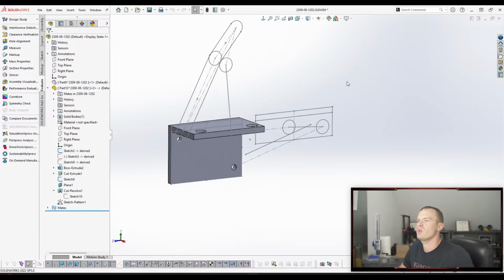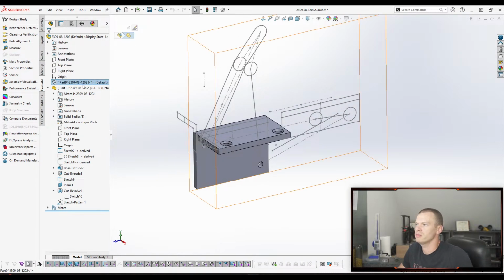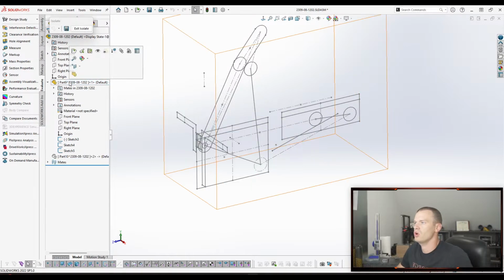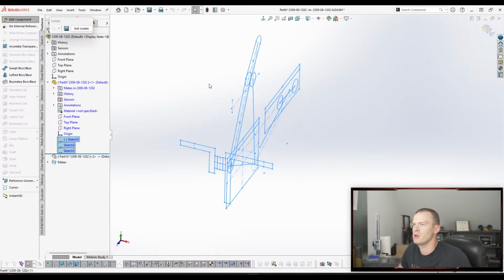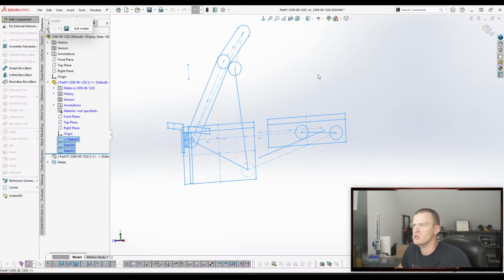All right, cool. So this is where we're at on our Hinge design, right? So we've created this kind of, I want to start calling this a folder part, because basically it's only here to hold all of our sketches, right? We've got 3 sketches that we've made up. So our primary one is this profile view where this morning we went through and figured out our linkage lengths, and then also we're designing it so that the links kind of bottom out on each other and control the movement. So we did that this morning.